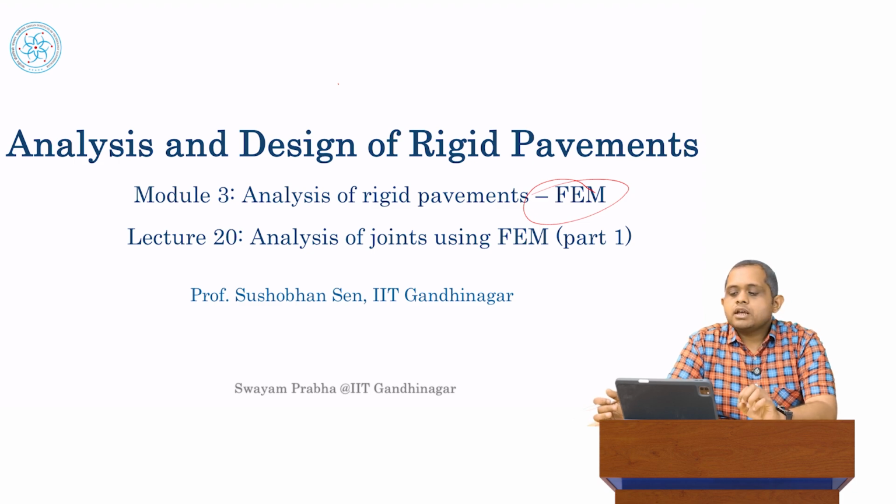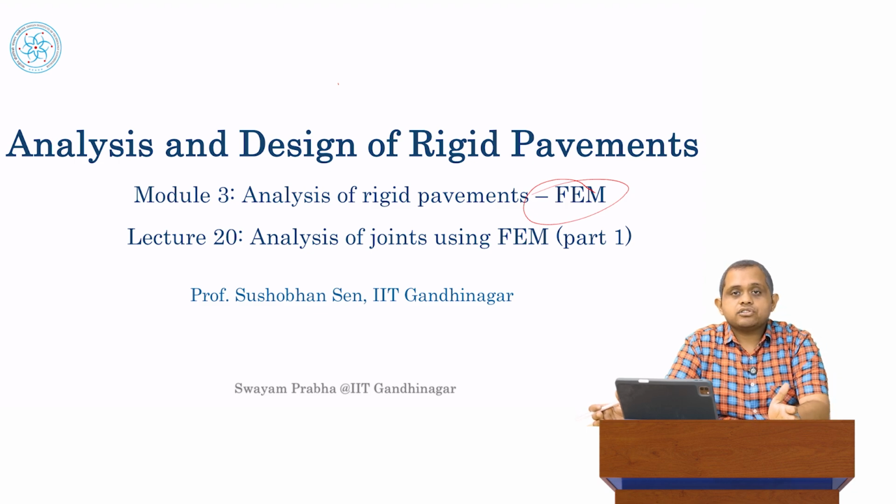Now, one of the things we learned about the finite element method, and indeed any numerical method, is we make a very astonishing assumption, which is that we give up on the idea of getting an accurate solution. Remember, analytical solutions are based on a series of assumptions. Westergaard's theory assumes circular loading, infinite slab, tensionless springs, etc. There are a number of assumptions that Westergaard's theory makes. Whether the assumptions are reasonable or not is a different matter. But as long as the assumptions are accepted, then the solution is exact. There is no error whatsoever in the solution. That's why we call it an analytical solution.